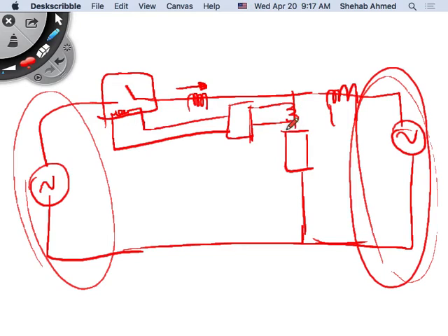This will disconnect what? The grid. But this will not see fault currents coming from your PV system, right? So a better place to put the CT would not be here, would probably be right here, right? So where you place the CT is important, right?